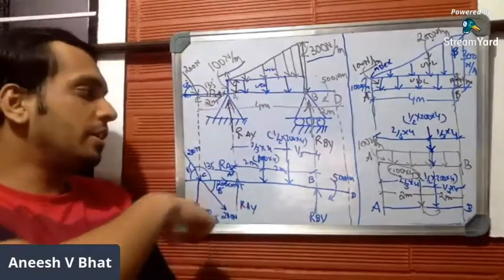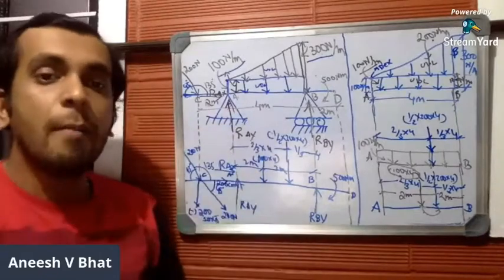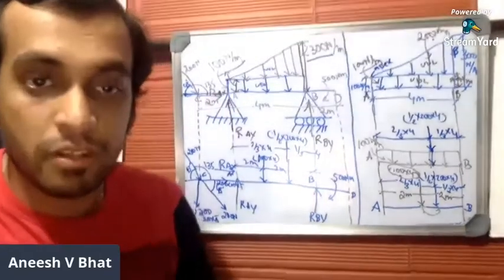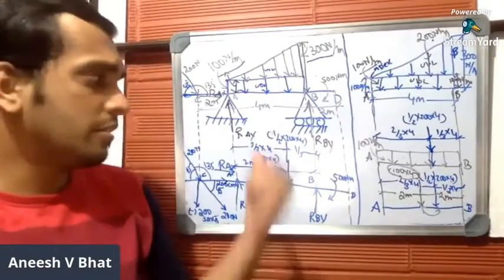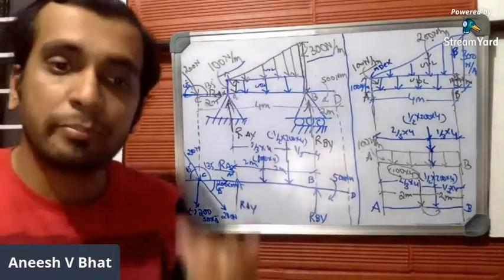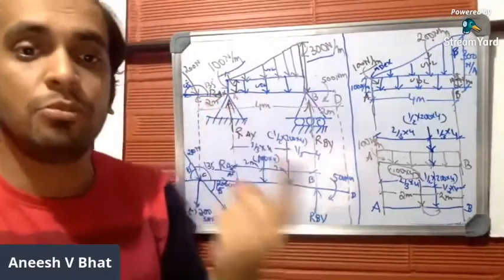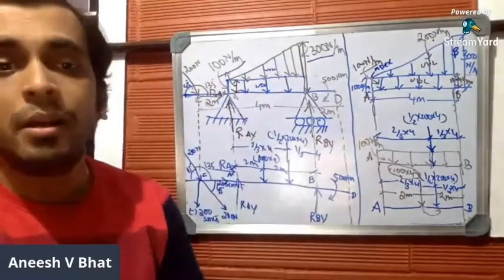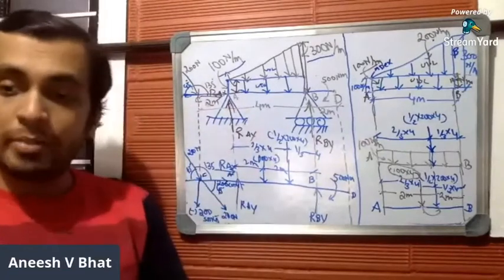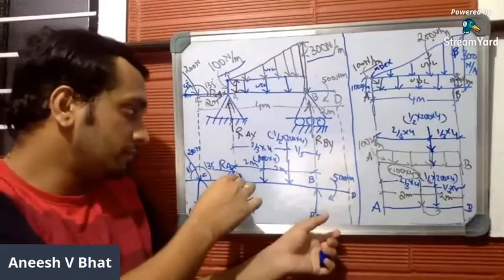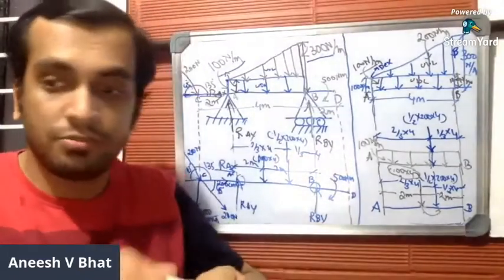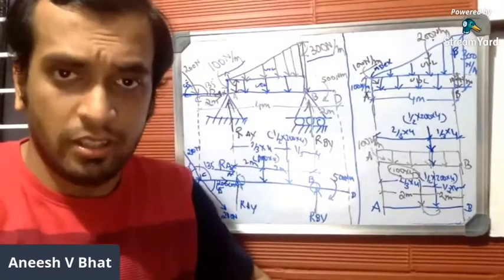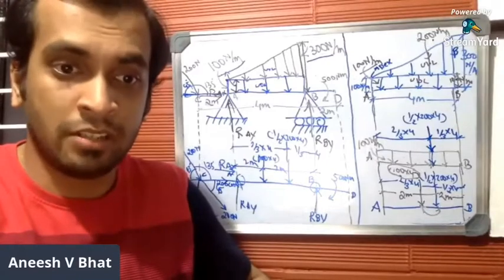So in this particular drawing, all the loads are in the form of point loads. Now, after drawing the point load diagram, it's very simple. You'll be applying 3 conditions of equilibrium: summation of Fx equal to 0, Fy equal to 0, and moment either about A or B. A or B is this point here. This is A, and this is B, not C and D, not the left extreme edges. Let me just take you through the calculation part.